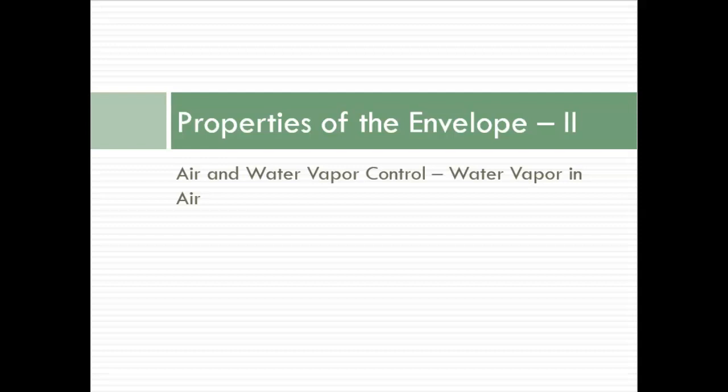However, although air and water vapor are thoroughly mixed together, the pressure exerted by the water vapor is independent of that exerted by the air. In other words, air pressure and vapor pressure act separately on enclosure surfaces.